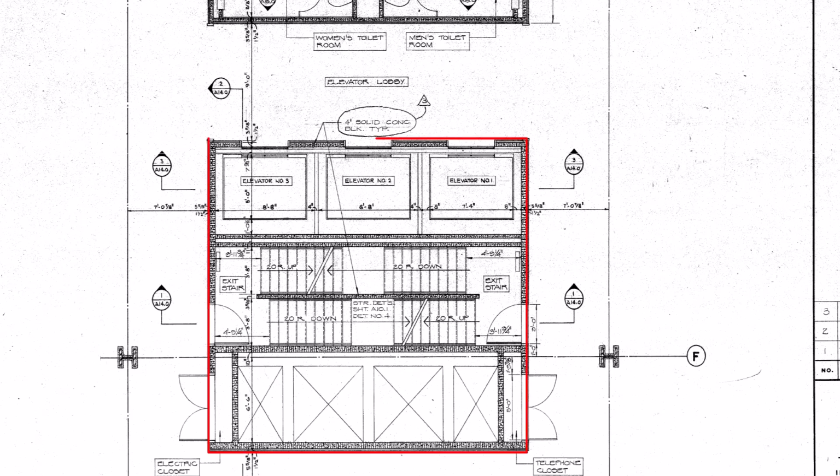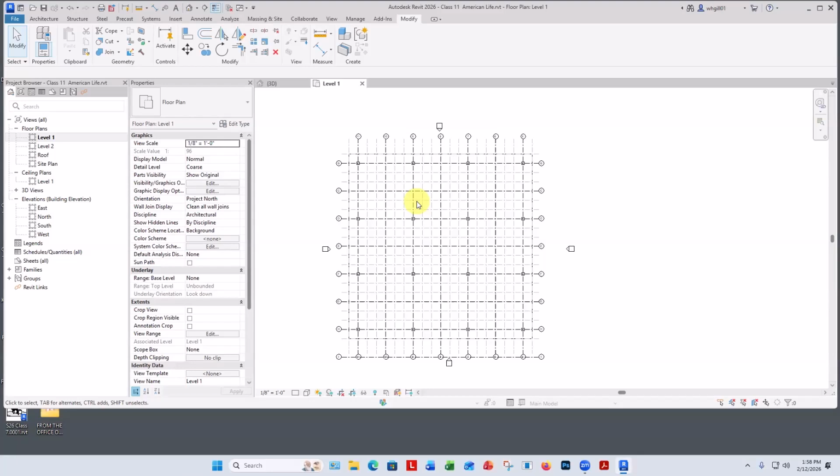Once we've got this thing drawn, we can mirror it about the center line of the building and put that up there. So we don't have to keep measuring and keep drawing. We can just know that this is very consistent here. Okay, let's see how that works. So we didn't actually measure anything, did we? And it's good that we didn't have to measure anything. All the information is there in the dimensions in one drawing where it should be.